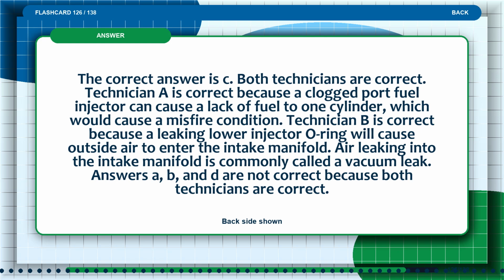The answer is. The correct answer is C. Both technicians are correct. Technician A is correct because a clogged port fuel injector can cause a lack of fuel to one cylinder, which would cause a misfire condition.